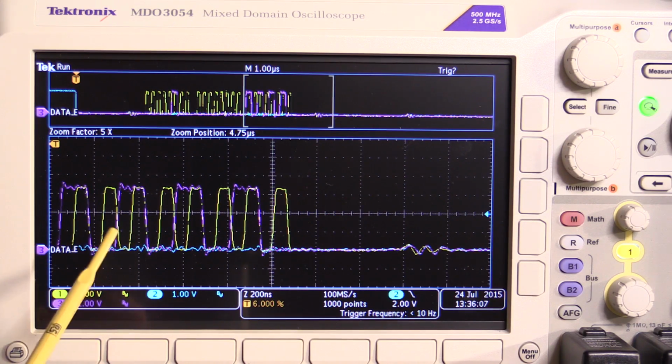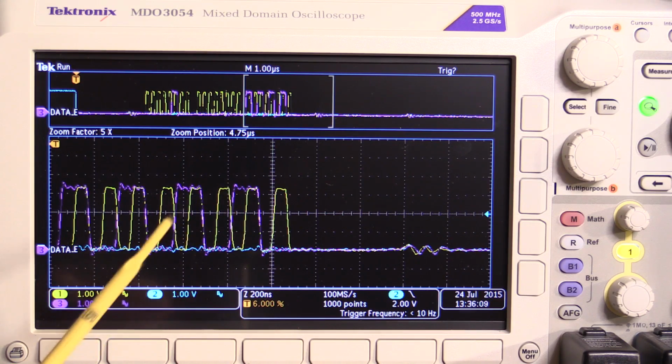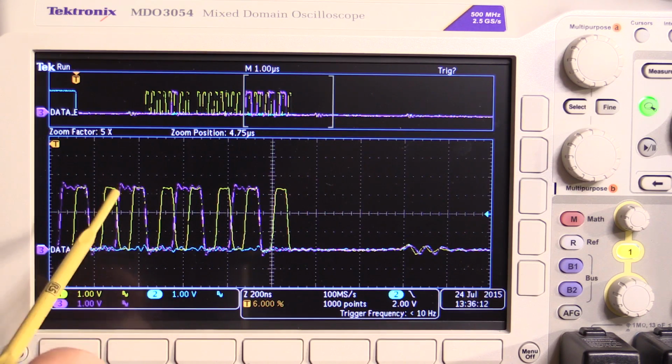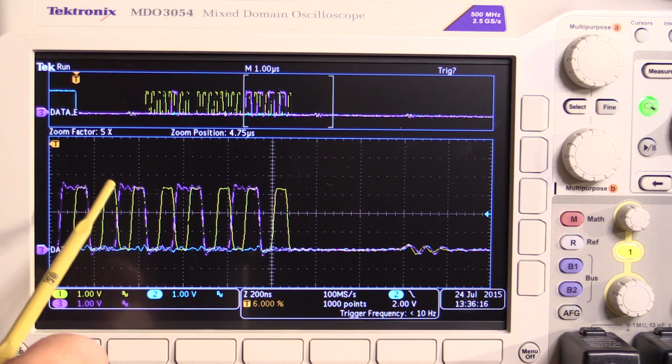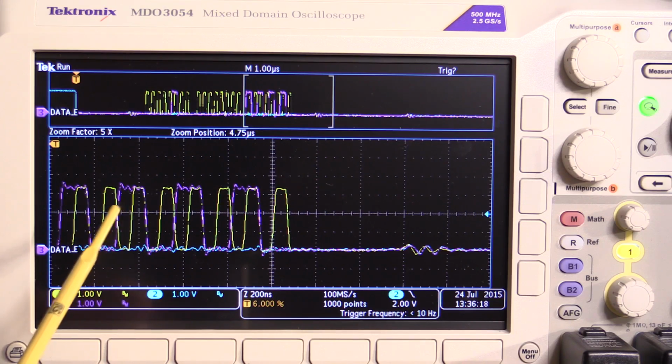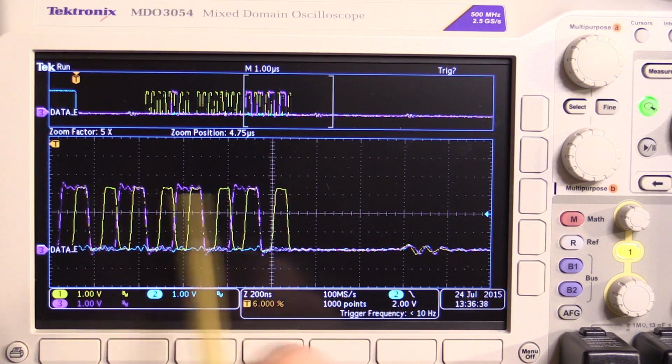But the slave device in our case, which is the DAC8734, is taking the negative edge to clock the data in. So now you've got the data going positive and the clock going negative at the same time. You tell me that you can guarantee what that's going to read, whether it's a 0 or a 1. It's going to be completely random. I mean, it may be predictable over a short period of time, but with temperature and various other things, it really is unpredictable. You cannot ever be sure of what's actually going to happen there, and that's mode 0.